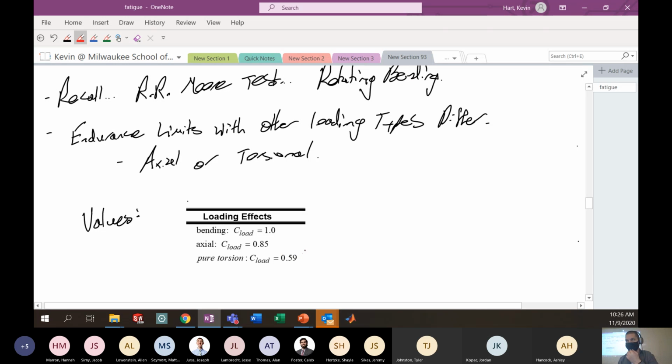It should be like a factor of 0.5. And so when you're putting something into pure torsional stresses, you have basically a pure shear situation going on, and you're modifying by about 50%, just like you do for max shear criteria. So not unreasonable to see a 60% modification for a pure torsional loading.